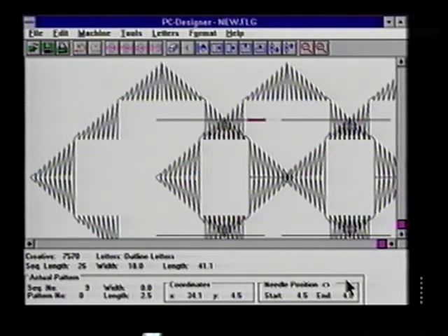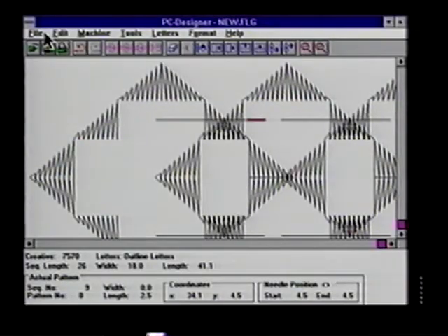Let's program in a scallop stitch program that uses directional feed. The directional numbers we will be using are found on the help screen under the title Open Stitch Program. Program in the following stitch program. We'll be using some shortcut keys to speed our designing. They are the F keys at the top of your keyboard plus the Control and Insert keys. Start with a new work area.